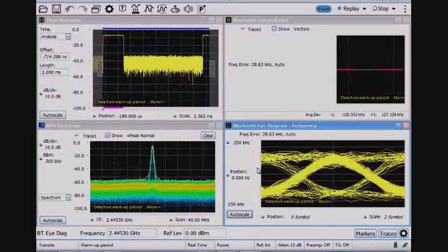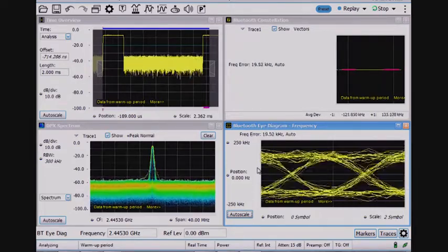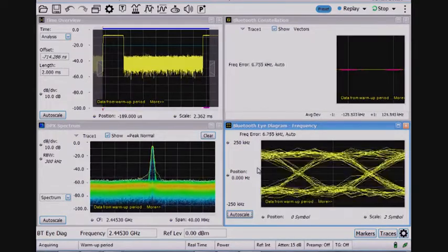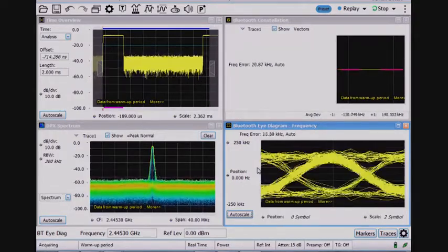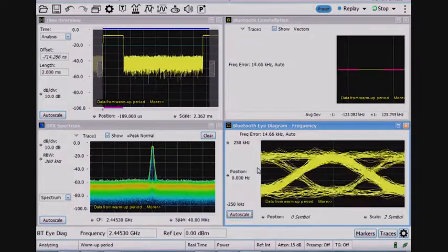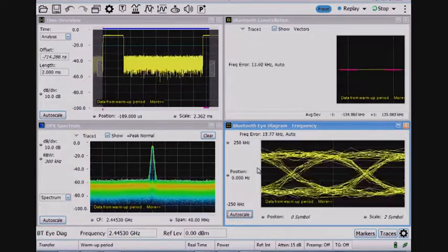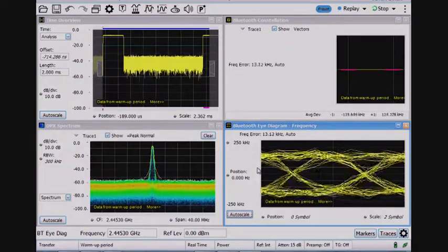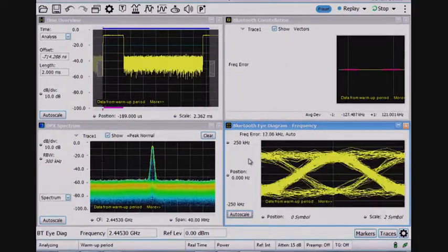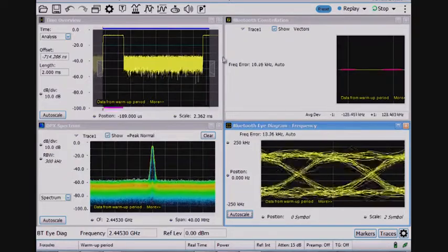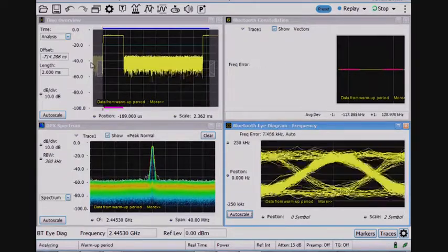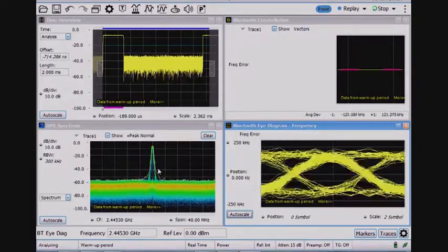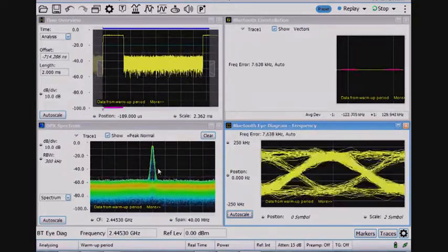This might be interesting, for example, if you have a new antenna design and you want to make sure you've improved the performance as a result of the antenna. This would also be helpful to make sure if you've made changes to the software that you haven't messed something up in terms of the physical layer transferring of the data. So make sure the constellation diagram is still clean. And I can see pretty clearly the time domain part of the signal, the RF envelope, like a zero span display, and the time overview, and also can run the DPX spectrum concurrently as well.